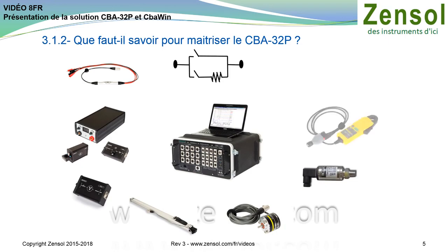Shown here is a Fluke 30A AC-DC current transducer. Another 20 and 200 AAC current transducer from AEMC. The CBA-32P's analog inputs comply with international interconnection standards. This makes it easy to connect any physical sensor from any manufacturer, with output voltages from 0 to 10 V or 4 to 20 milliamp. This is the open architecture to which we referred earlier.